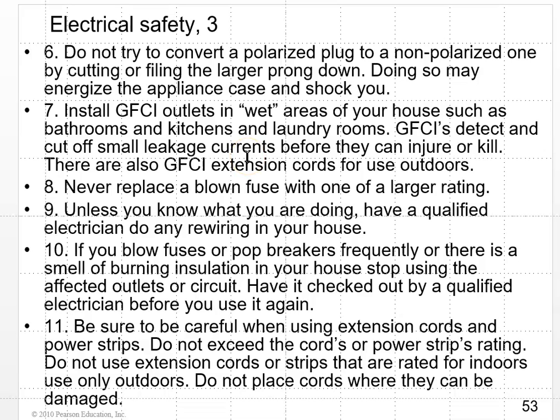Install GFCI outlets in wet areas of your house, such as bathrooms, kitchens and laundry rooms. There's a code, I think it's 6 feet. Any outlet within 6 feet of a source of water should have a GFCI in it. GFCI stands for ground fault circuit interrupter. They detect and cut off small leakage currents before they can injure or kill. And there are actually GFCI extension cords, which can be used outdoors.